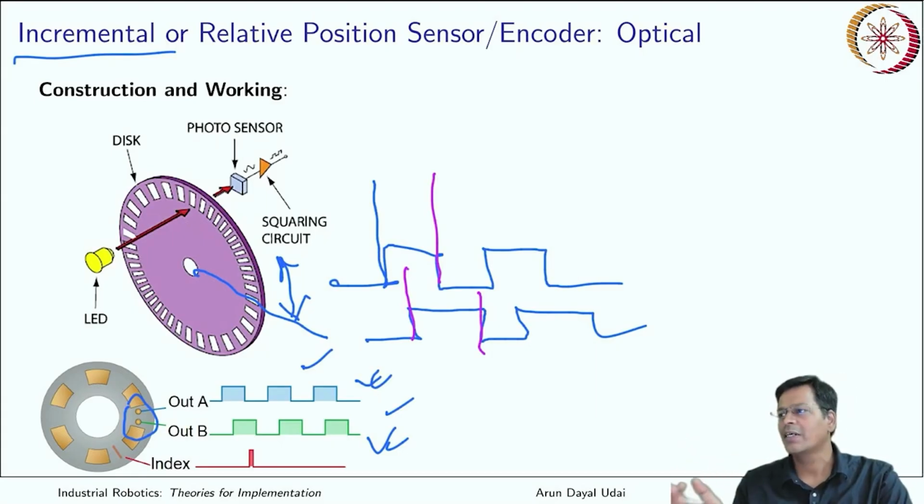One slot turn is converted to at least 4 different signals, which you can use to resolve it into 4 independent instances. So just one slot is further subdivided. It is not very complex, but this is the way you can get more resolution out of just one window count.